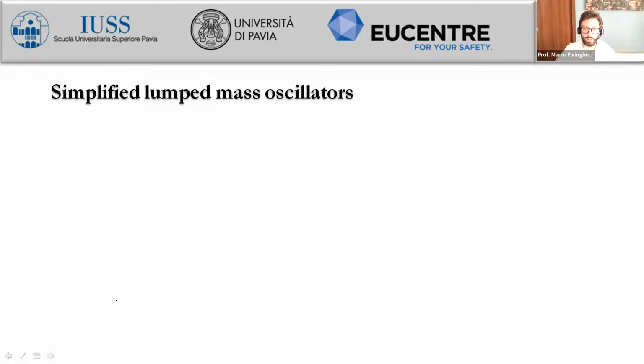We discussed at the very beginning of this short course that the overall structure, for instance, a building which is base isolated through particular devices, can be directly associated to a single degree of freedom, because, if you remember, we associated the overall system to a series of two springs. We neglected approximately the mass of the plate, which is the interface between the superstructure and the isolation system, so that we were able to compute the expression for the equivalent stiffness of the series of the two springs. And then by considering the stiffness of the building, which is much higher with respect to the stiffness of the isolation layer, since we are going to provide the proper period shift, we can have the overall system simplified as a single degree of freedom oscillator, where the mass is the total mass which is above the isolation devices.